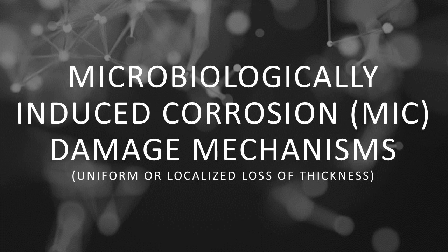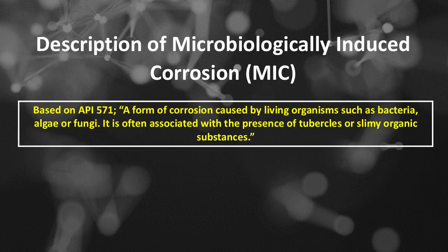Microbiologically induced corrosion, or MIC, damage mechanisms is a part of uniform or localized loss of thickness. Description of microbiologically induced corrosion based on API 571: a form of corrosion caused by living organisms such as bacteria, algae or fungi. It is often associated with the presence of tubercles or slimy organic substances.